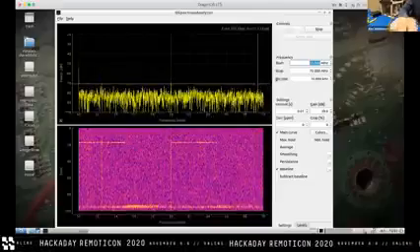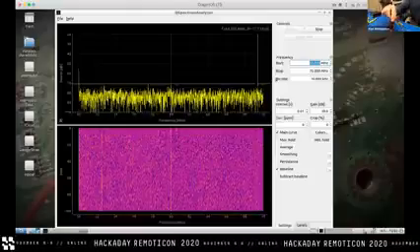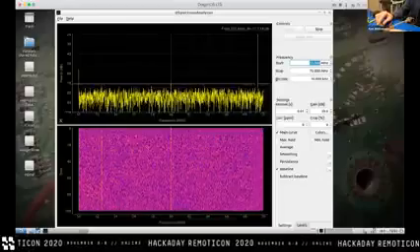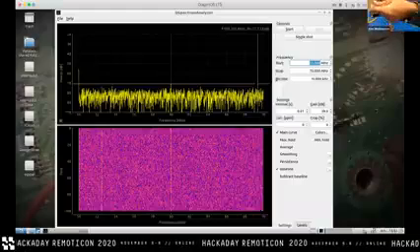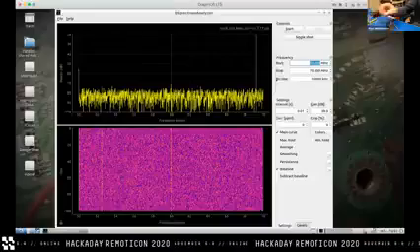Nice spot. And actually, a secondary point, because the HackRF does not have a bias tee built in, we're going to have to power the LNA from an external source to make it even turn on. So that makes things more interesting. It also did I click?